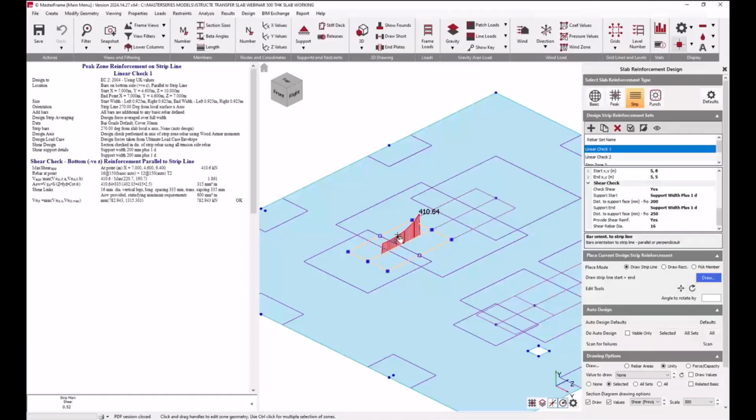So it will determine which point along this whole strip, albeit the IStructE document tells us to sample the reinforcement simply at a 1D section away from the supported column. But we're going beyond that, and we are doing that, but we are checking all the points along the strip averaged over the 4D width, because it's quite possible that you could have a lesser value of shear force as you perhaps move away to an area where you have tension on the bottom of the slab with a lesser amount of reinforcement. So you'd have a lesser value of shear force, but also a lesser capacity.